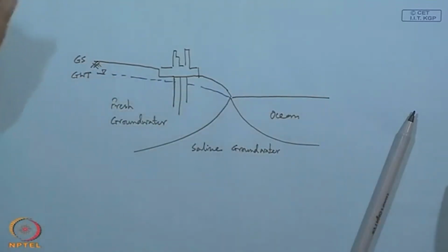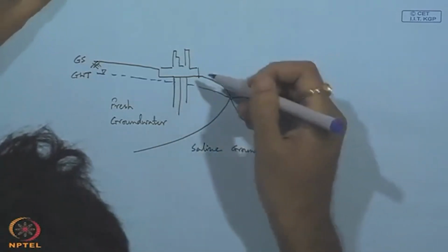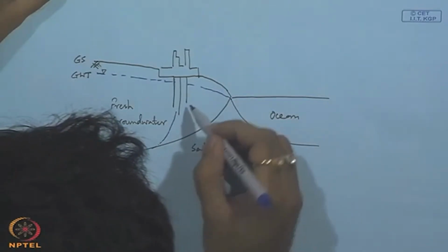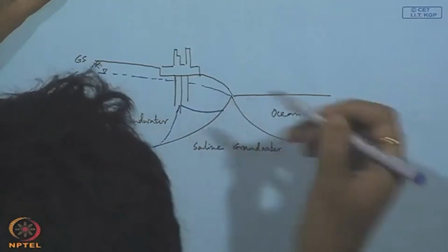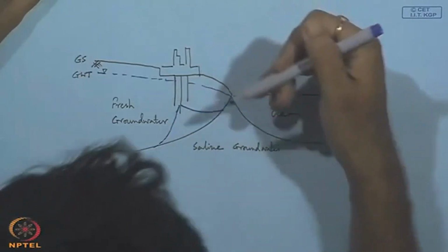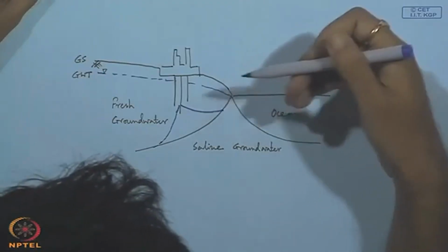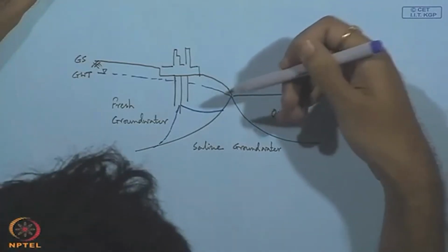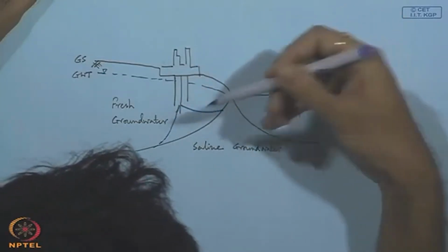What happens due to constant pumping from city well field, there will be a gradual movement of this interface towards these wells, and finally, if these wells draw significant amount of water from this freshwater aquifer, it can cause saline water intrusion in groundwater aquifer.